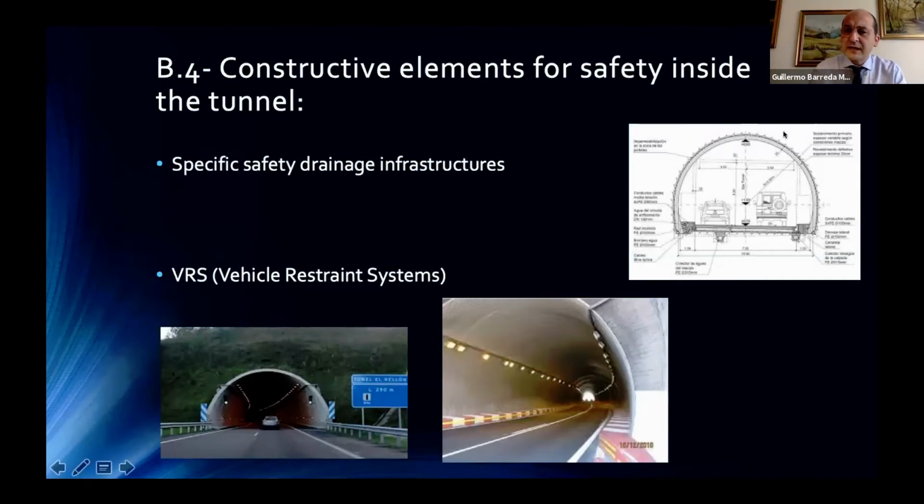There are other systems like hydrocarbon separators to receive the spills from the traffic, from the trucks, to receive these liquids and separate them to pour it into the environment and to avoid any pollution. These hydrocarbon separators are outside of the tunnel, and the stream of the spill must be directed to those hydrocarbon separators. So the specific drainage is very important to be studied when doing a road safety audit.